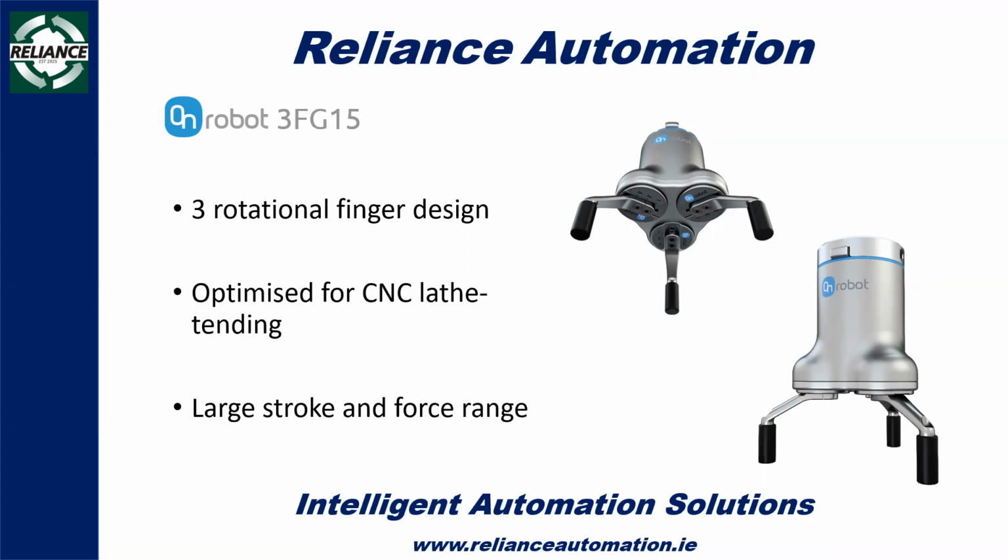They're also, again, same with lots of the OnRobot pieces, very adaptable. So you can move the grippers in and out depending on the piece that you're looking at. You can also change the material on the end of the grippers. So you see there, they've got the nice rubber soft fingers, but you can also remove that so that you've just got the steel on steel contact for pieces that might be a little bit heavier and you require a larger clamping force onto.